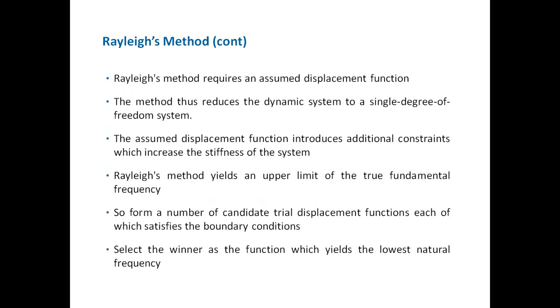Just to give you an overview, the Rayleigh method requires an assumed displacement function. And we're only going to do a single degree of freedom analysis, so we're only going to assume a single displacement function. Now, if there were a need, we could do an extension to the Rayleigh method, called the Rayleigh-Ritz method. We're not actually going to cover that today. Maybe in a future webinar we will. But the finite element analysis method, which some of you are familiar with, is actually an extension of the Rayleigh-Ritz method. So I will mention that.